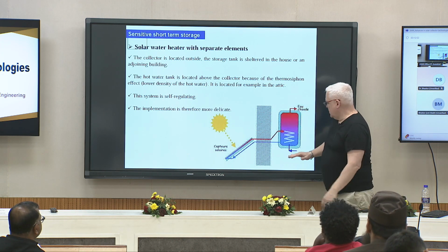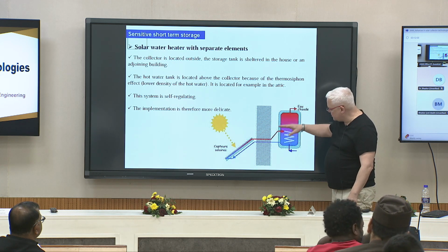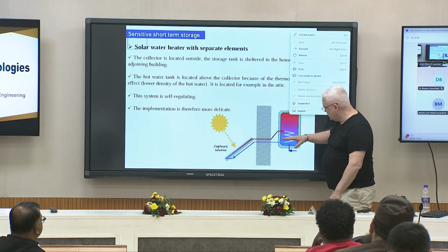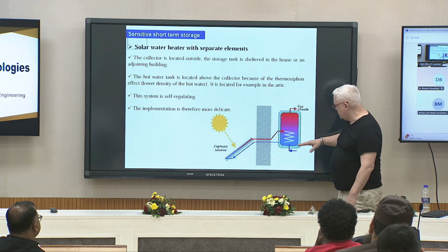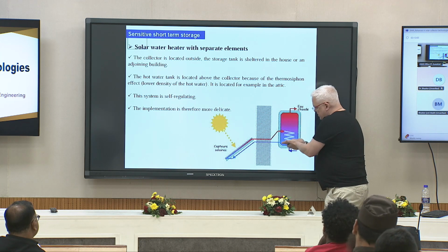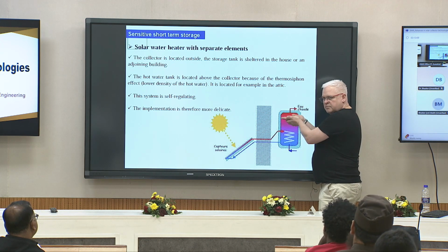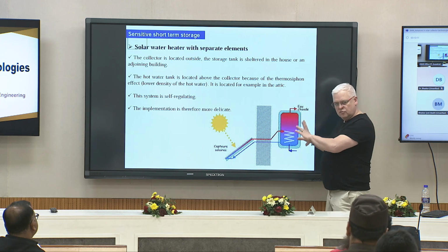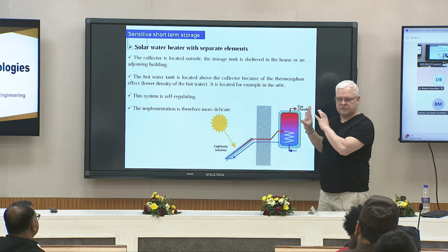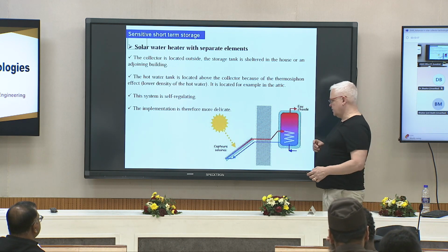Okay, here you can have 20 degrees, 25, 30, until 80. So it's well stratified. That means that the cool water, when you are injecting and you're extracting at the top, will progressively come without mixing, so that you can use 80% of the solar thermal energy that you have stored in your tank.